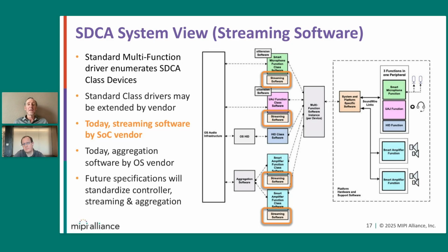Those today are separate drivers from the functionality within the operating system. So the class drivers themselves don't actually get involved explicitly with the streaming behavior. That's provided as a separate driver stack that today is predominantly still making use of the SoC vendor host controllers to provide that functionality, but again, is not impacting the peripherals at all. The peripherals today are using the standard transport, data port, and streaming methods, and don't have to worry about what's happening on the host side of things.